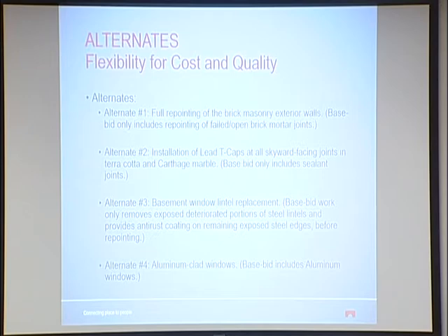Alternate number 2, installation of lead T-caps at all the skyward facing joints in the terracotta and the Carthage marble. A lead T-cap is a product that you can install in those sealant joints on the skyward facing surfaces that makes them much more durable over time.